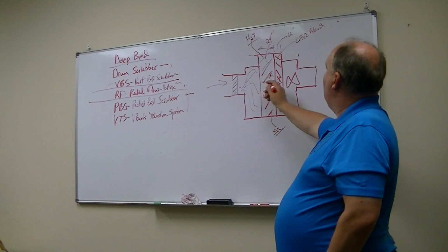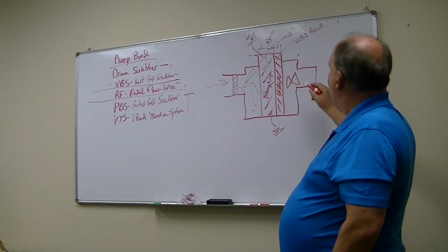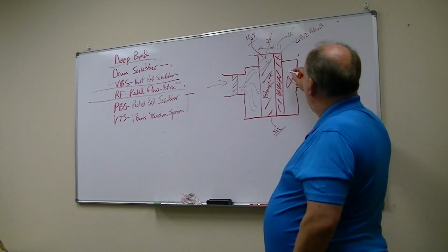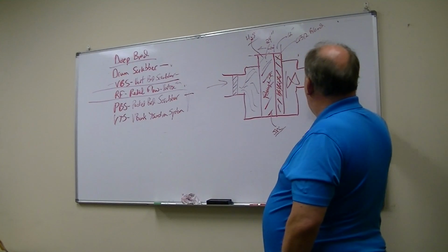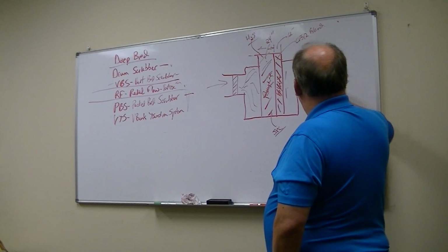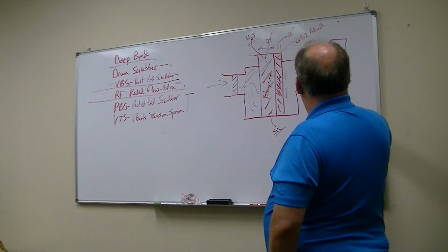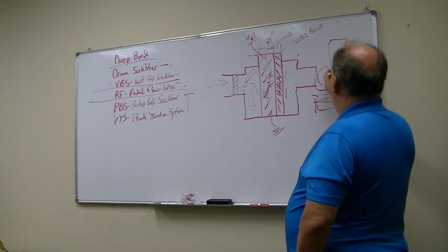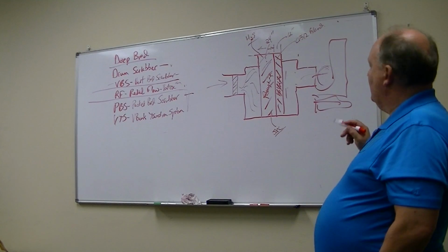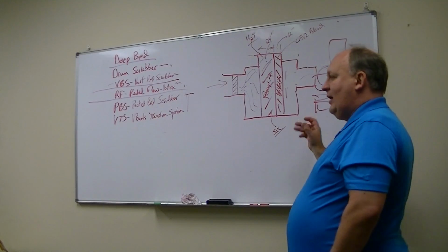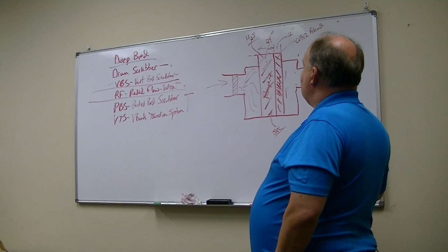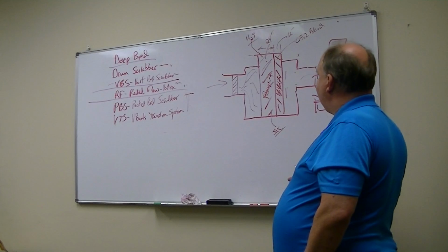So that's how we would typically do it, and then we're typically going to work on some type of draw-through blower. It's either going to be a plenum fan inside the housing, or it could even be an external blower that's pulling air outside, okay? There are different advantages for inside and outside blowers, and we can talk about that in a little while as well. So this is a typical odor control design.